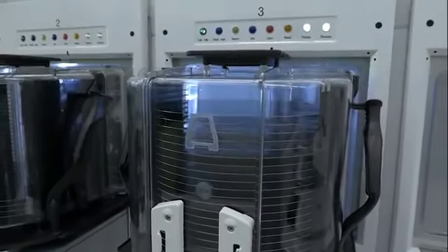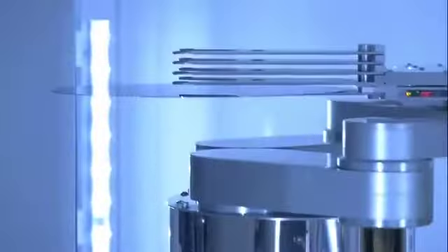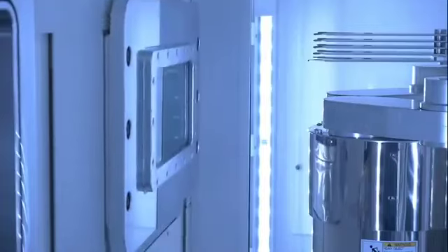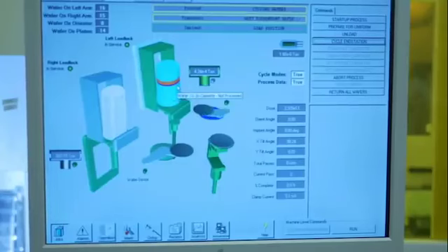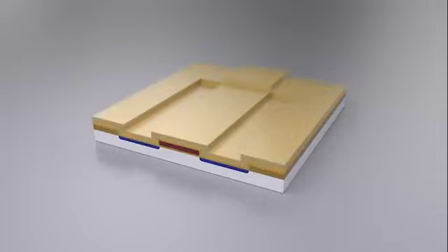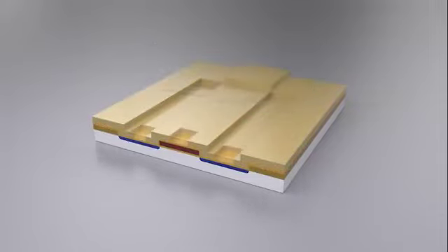The next step is the doping process, where impurity atoms are introduced into the exposed silicon. An ion implanter is used to shoot impurity atoms into the silicon. This changes the conductivity of the exposed silicon by fractions of a micrometer. After the photoresist residue has been stripped, another oxide layer is applied. The wafer undergoes another cycle of applying photoresist, exposure through the mask, and stripping.